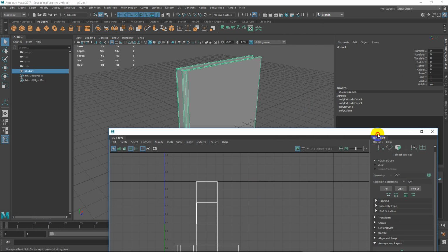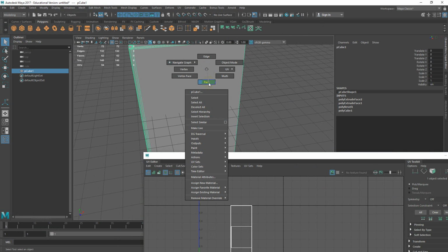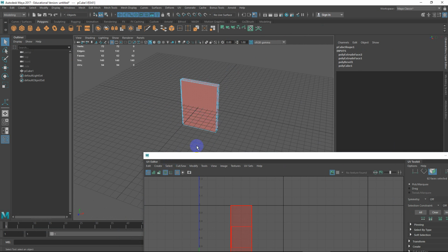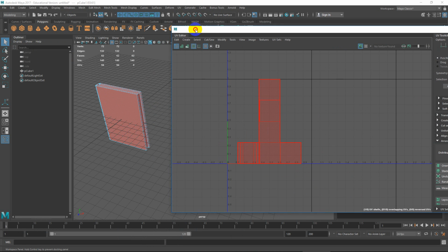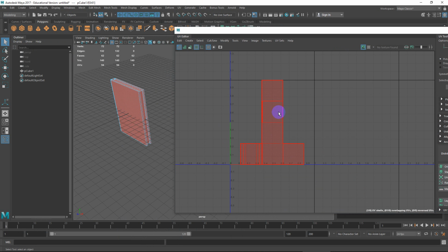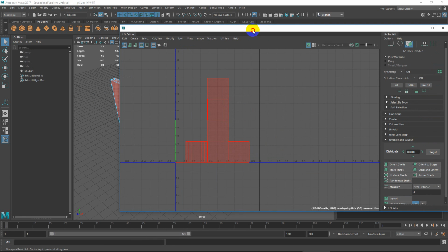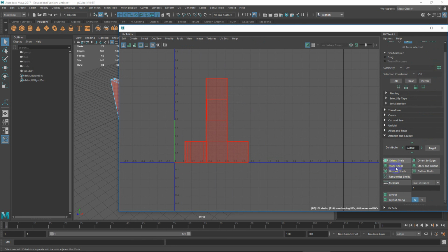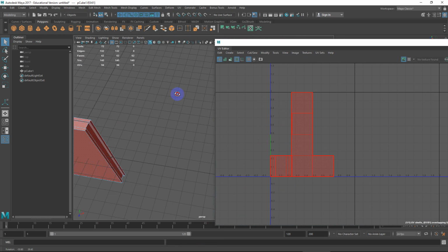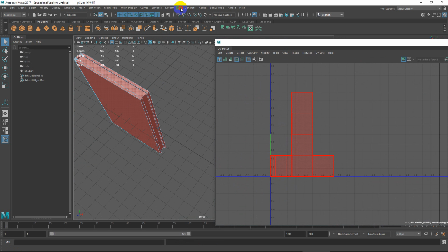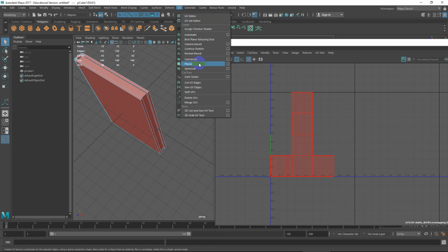So in this case, I have kind of a couple of cheap methods that I use. The main thing is to get some sort of UVs into this object. Now, since it was started from a cube, and it's not too far removed from a cube, it still has a lot of its UVs there. So I could try to just go to layout maybe. It's not great. And it's also not particularly accurate, but yeah, what I'll often do is just kind of throw one big quick UV on the whole thing.